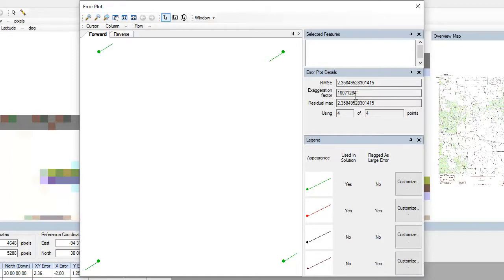You can also look at that in the reverse direction. So from the other direction, coming from the reference coordinate system and predicting what pixel location we'd be at, we're doing pretty well there as well. So we have fairly uniform distances across these. That's one thing that we want to see. They're also not following an exact pattern. There's a slight kind of rotation here that we could look at shifting a couple of pixels if we wanted to get this even more perfect, but this is definitely within a good expected residual error. My maximum error here is about 6, so that's nice and low.